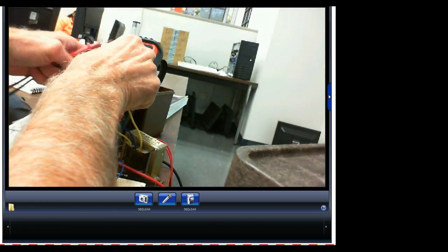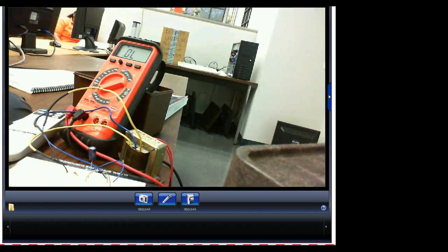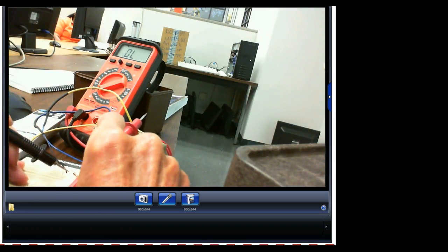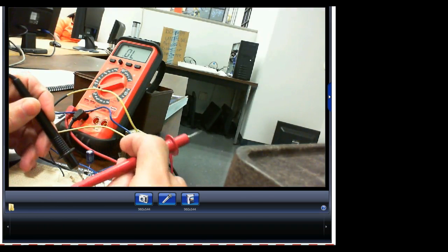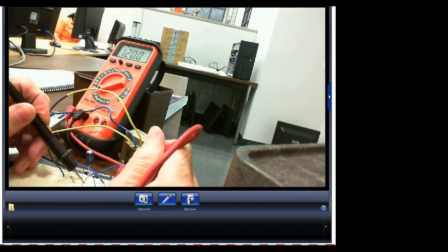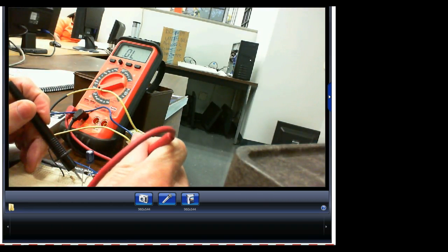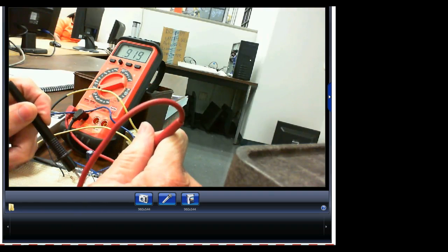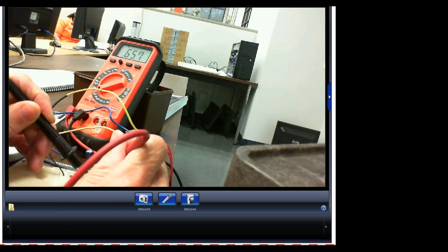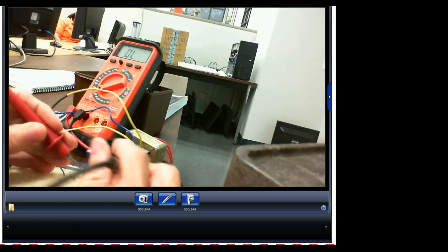Yeah, use the diode scale. If you don't, you can just use a high ohm scale. First of all, we try to check it in the circuit. What I'm going to do is forward bias it. Let me get this other diode out. This is halfway. I'll show y'all some problems. We'll look across it, and it's measuring about 7/10, if I can get into it. Then when we reverse bias, it should measure open.